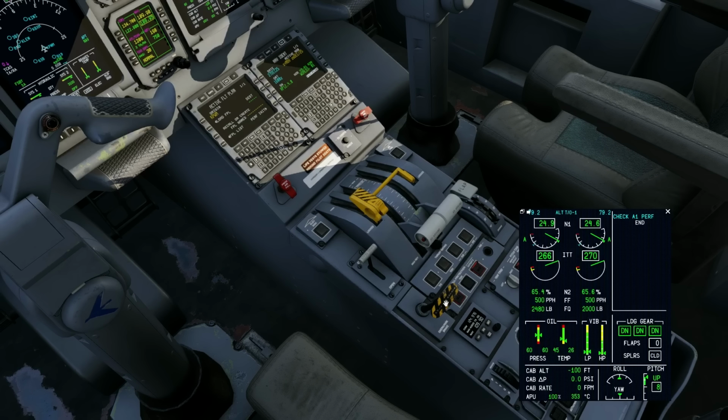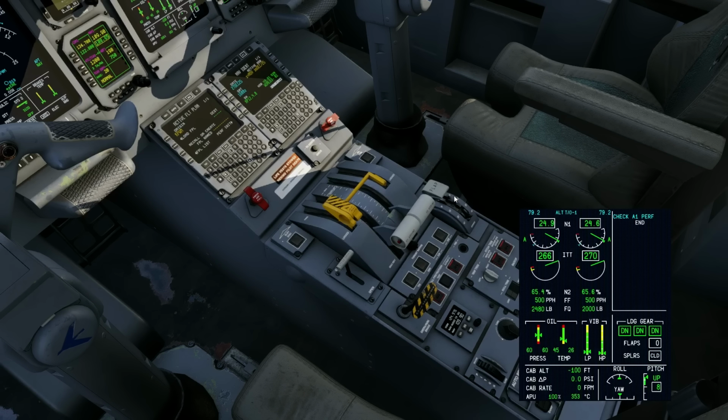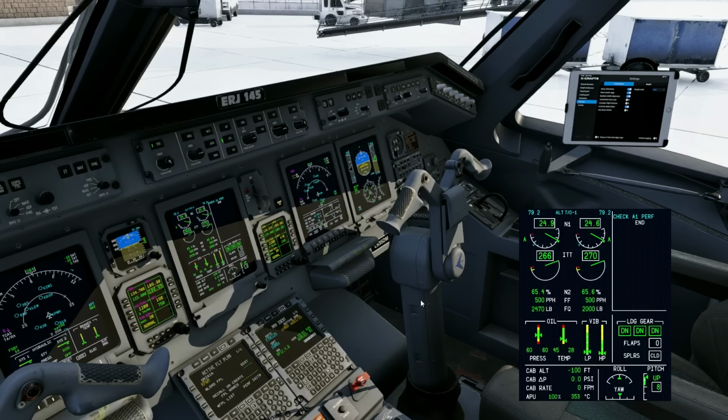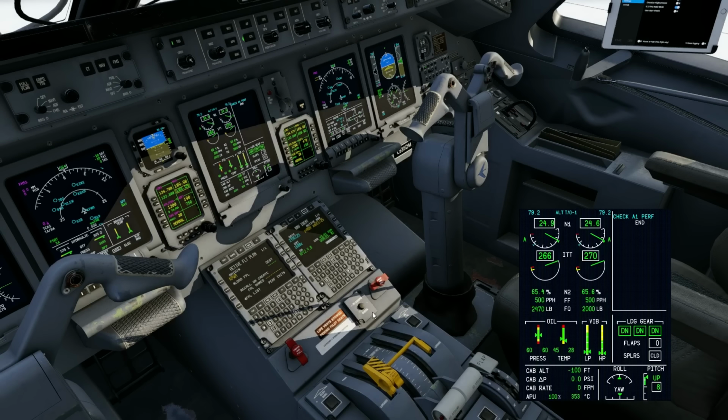I seem to have a brake set, and I don't seem to have flaps. The computer doesn't quite register takeoff conditions, which would be the brake off and the flaps set. So it's not quite a takeoff config warning. We still have no takeoff config, which checks flaps, spoilers, trim, and brake. So we still have that. That's our failsafe. If we push the power up and we get that ding ding ding, that's actually our takeoff config. But this is sort of a mini takeoff config is how I think about it.